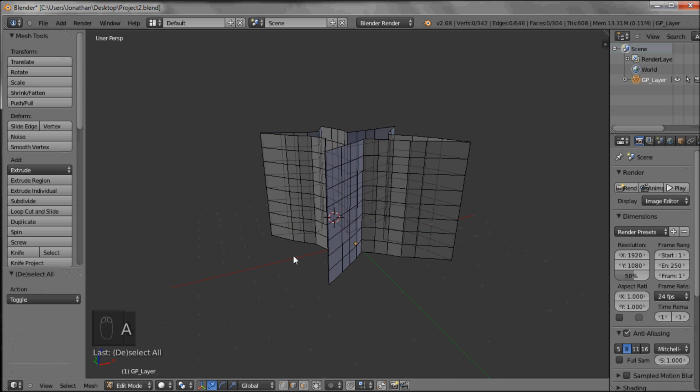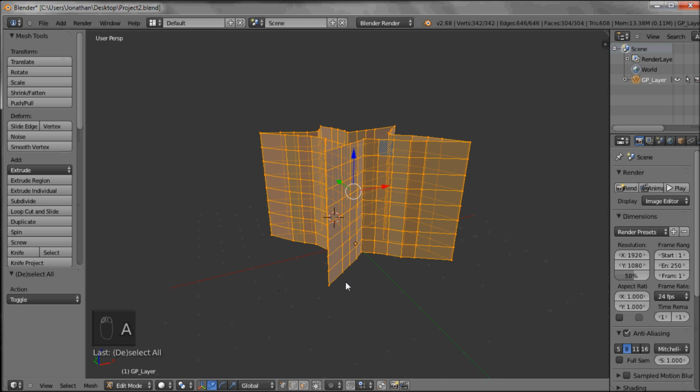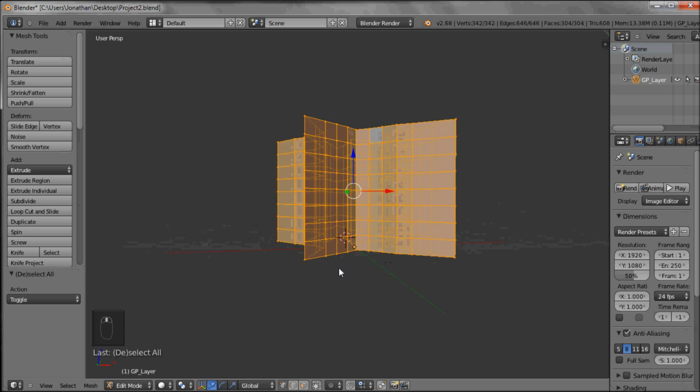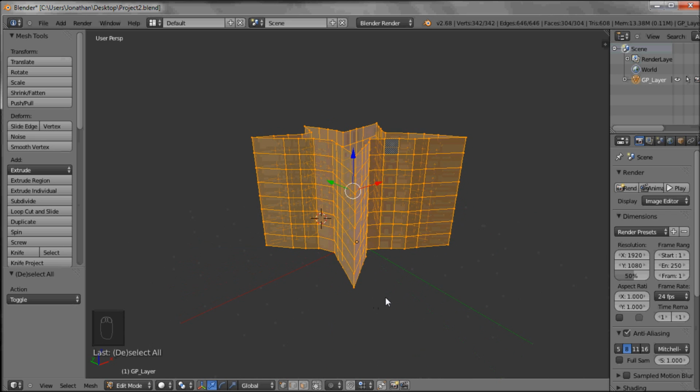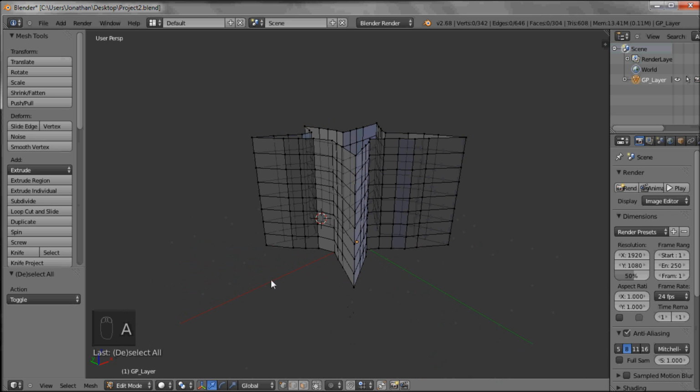Right, so deselect that. I prefer modeling with vertices, so I'm going back to vertices. Now if I press A to select all, you can see there are spots all over now. Deselect that. With my right click, I could grab one vertex, press G for grab, and you can see that can be manipulated. Right, Control Z is undo.